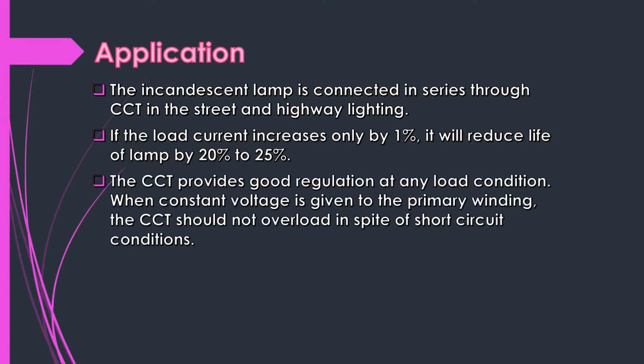The constant current transformer provides good regulation at any load condition when constant voltage is given to the primary winding. The constant current transformer should not overload in spite of short circuit condition.